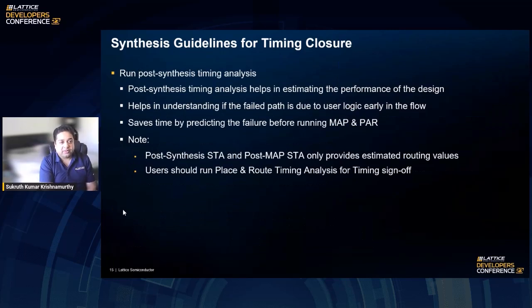It is recommended to run post-synthesis timing analysis. As I mentioned in the past, post-synthesis timing analysis will help in estimating the performance of the design. It can help you understand if your failing path is because of the logic or because of the estimated routing. If this is because of the logic, it saves you a lot of time by predicting the failure before running map and par.